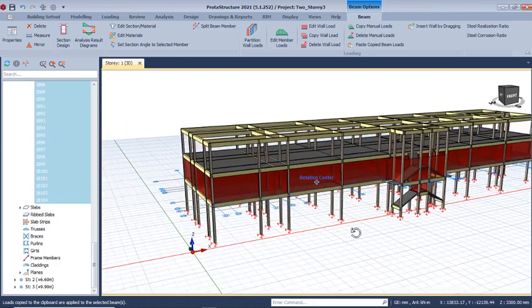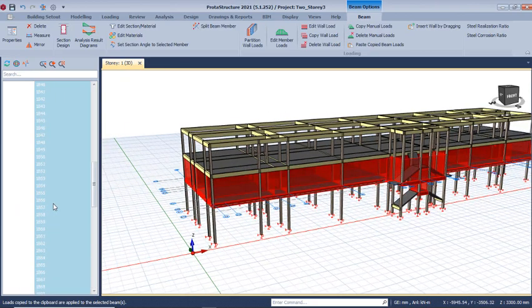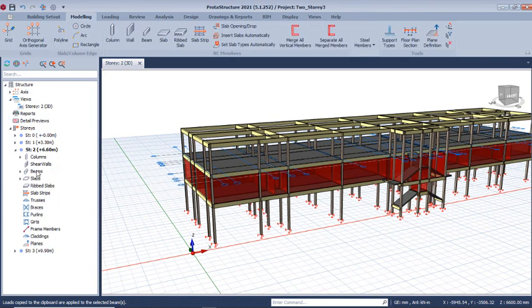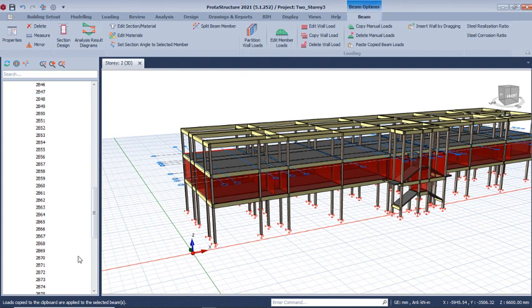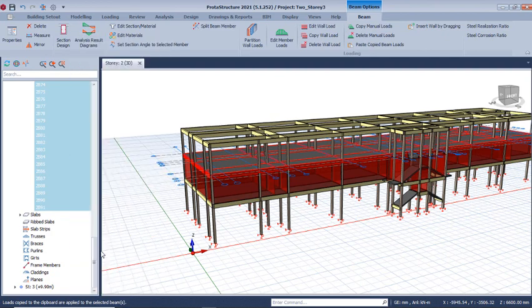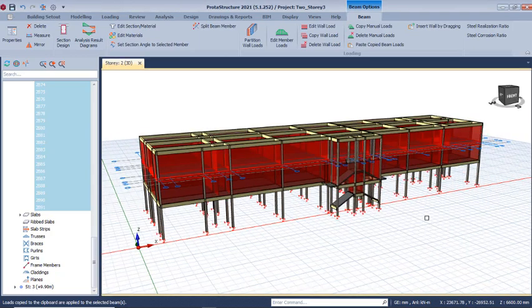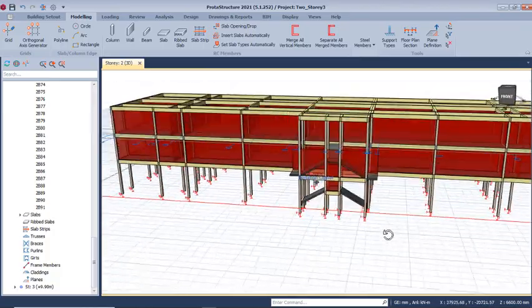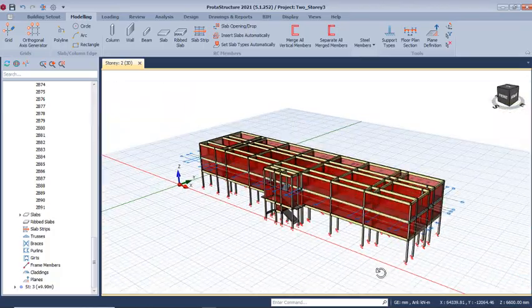So we navigate to story 2, and we repeat the same thing. You minimize this, navigate to story 2, and then expand this, select the first one, hold the shift key, select the last one, right click, and then paste. Just like this. So you'll be having something of this kind. So we have fully loaded the structure like this.